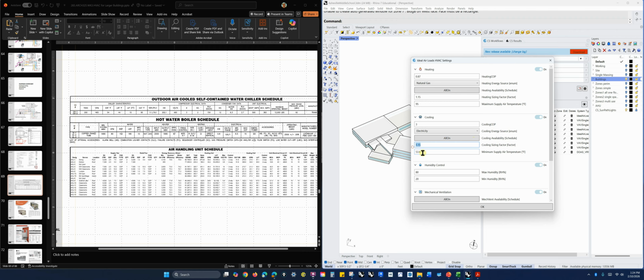Then again, we have the sizing, and the minimum set point temperature is 53.5. I typically see 55 for this as a rule of thumb, and I would have put the heating one at 100 or maybe even 110. But these are fine. So this is showing me, yeah, I get this at least, and we'll see why in a minute. This is why these have an effect on our sizing. What we're saying is that we're delivering air of this temperature when we're cooling, and air of this temperature when we're heating. Just remember that we're going to be talking about that.